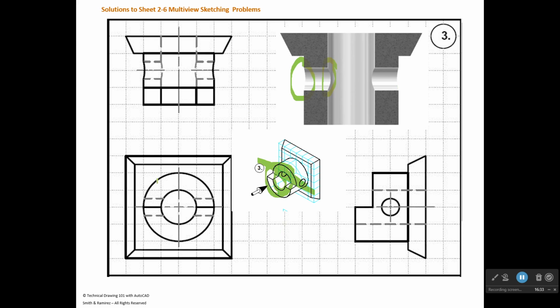When you draw that, you draw your larger circle, your smaller circle right there, and then you draw this guy running all the way through. What happens is if you go over here and you see where that hidden line hits versus where the edge of the cylinder is, the cylinder is actually in line right there with that grid. But you go from where the hidden line begins, and it's going to be inset just a little bit to right there. And so there's a little dip right in there.